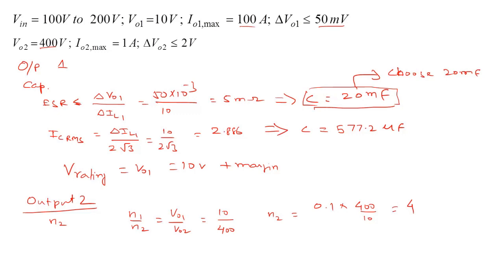Okay. The Dmax and Dmin are common for all the windings, all the voltages. So Dmax is 1 and D minimum is 0.5. There's only one control freedom, which is the D, just one duty ratio for the entire converter. It does not change with multiple outputs.